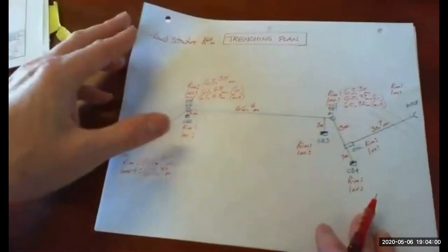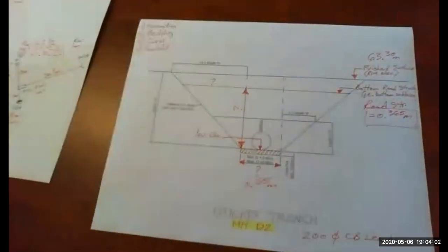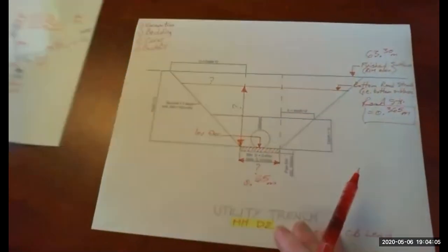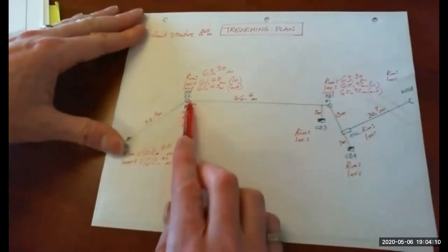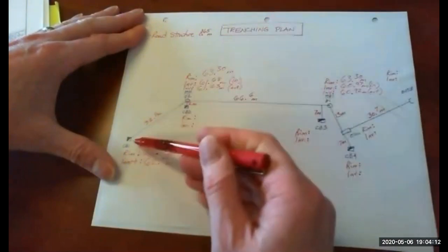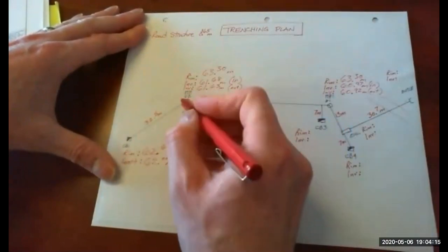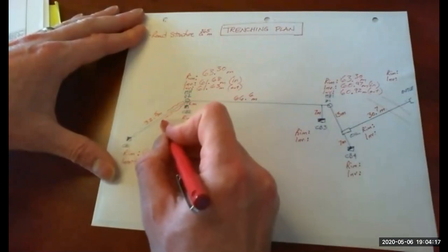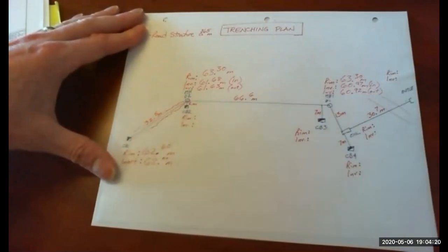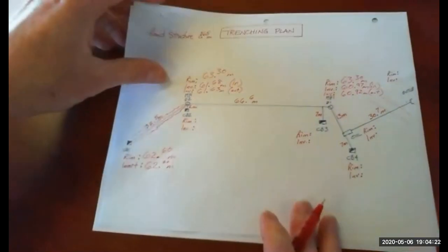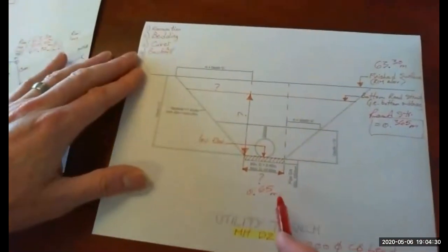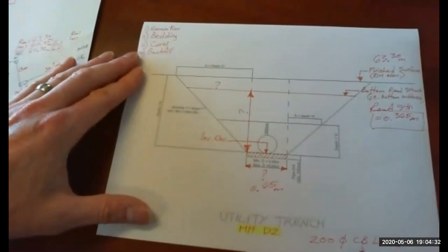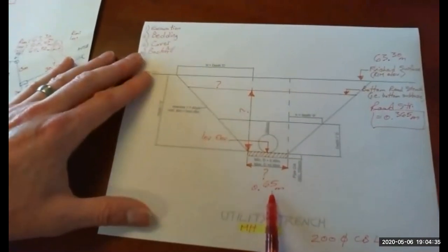Okay, so we go back to, so we're at this manhole. Get back on the screen there. We're at this manhole. We're looking that direction at the catch basin. We're looking at this trench. So this one here, all the way along. We're not looking in that direction yet. So the width of our CB lead trench, again, is the same, 0.65.